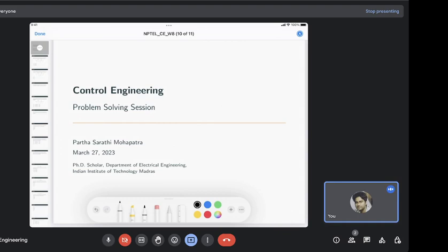But now we see that we should place this pole to the right of this zero, so that it will have this dominant effect. So the total angle contribution of this compensator will be negative, because this pole is located near the origin and this zero is located to the right of this pole for this compensator, and thus it is called a lag compensator.